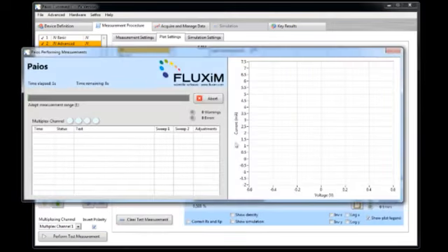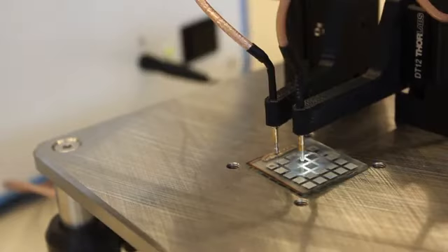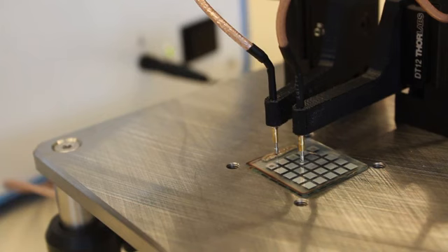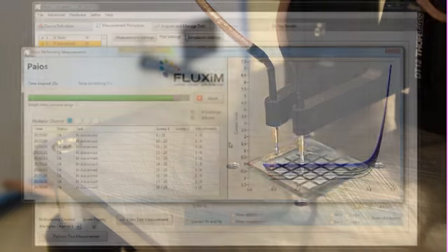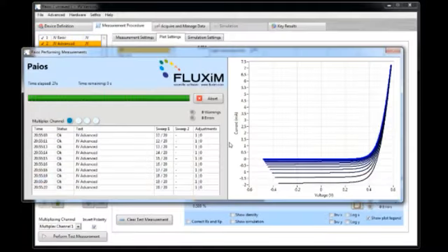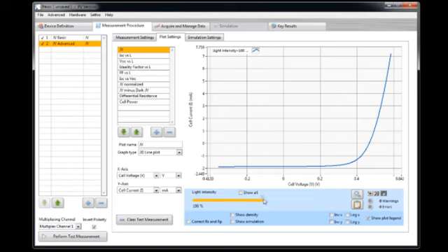When I start the measurement, here again we see the preview window. We can now look at the cell and we see how the cell is illuminated bottom up by the LED. Each time the LED gets brighter, because we now measure different IV curves at different light intensities. So the measurement has now finished. We can now browse through the data.